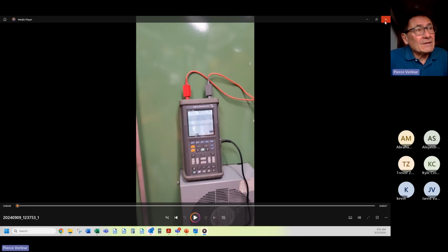Now, what about those long motor lead lengths and that tank circuit and the change in capacitance and impedance associated with that circuit? Why were those drives immediately over current tripping? By the way, when they ran it in open loop, we didn't have tripping on the permanent magnet motor, and I haven't figured that one out yet.